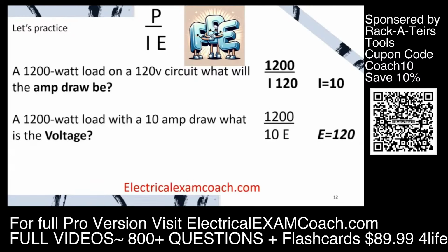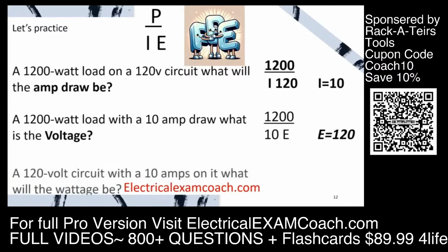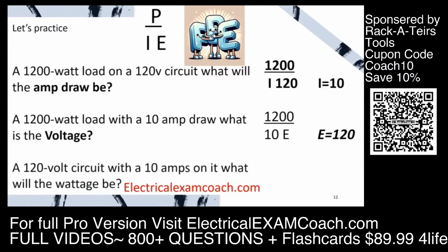We know our wattage and our amperage, and all we're looking for is to solve our voltage. So we divide and we get 120. And if we have a 120 volt circuit with 10 amps on it, what will the wattage be? That's right, all we have to do is multiply it out. And when we multiply 10 by 120, that equals 1200 watts.